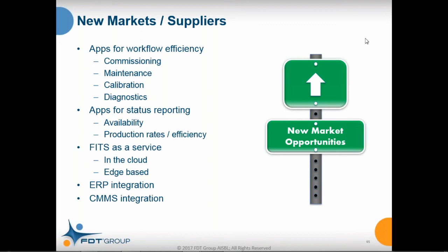Other areas that we could see that people would be interested in, integration to ERP and CMMS is a big space, and whether they do this with OPC UA or whether they do it with our WebSockets capabilities, that's for them to decide. I think most of that would go the OPC route just logically, but there's a service model there as well. Just because you have OPC on both ends of the hose doesn't mean they're ready to just start exchanging data freely. Work has to be done there. And there's definitely a service layer in there for some company that's interested to do that kind of work. Same with, even if you're just integrating into a computerized maintenance management system, there's some integration work that has to go on there.